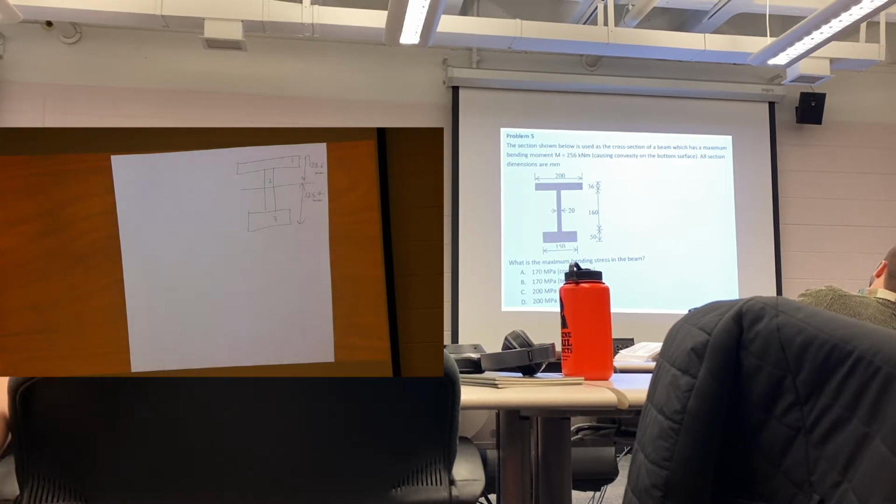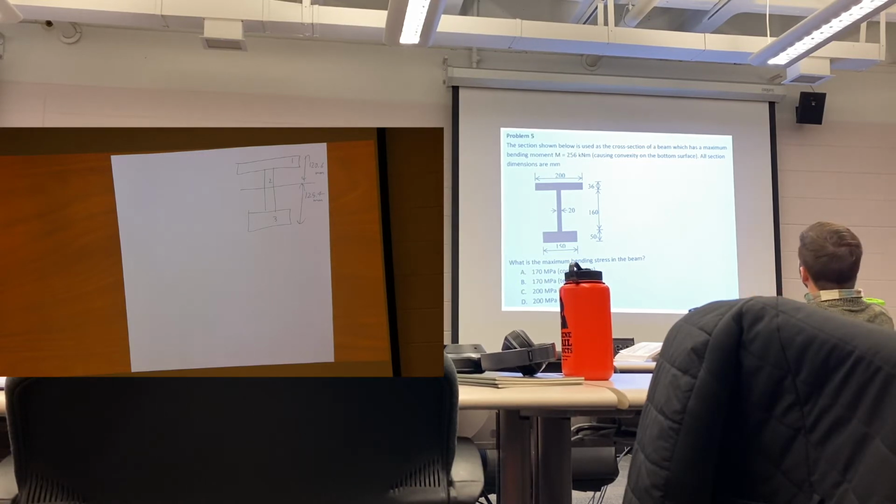So this was a close call actually. You had to verify this, but since the bottom area 150 by 50 is 7500 and 200 by 36 is 7200, but this is more spread, so it's a little bit further, it will pull it slightly up.